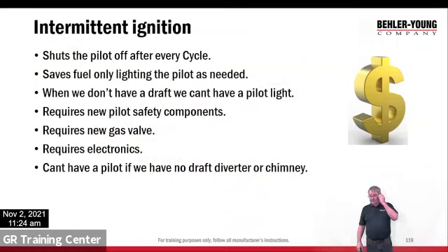All right. Now, again, as we progressed into more efficiency, pilots were expensive, right? Because you had to keep them running. You know, one pilot at 100 BTUs isn't much, but how many millions of pilots were going around the country? So the next thing we wanted to do is get into intermittent ignition. We didn't want a pilot that was lit all the time. So we wanted intermittent ignition. So it lights the pilot only when we need to light the furnace and then shuts it off again. Saves fuel because we only light the pilot when we need it.